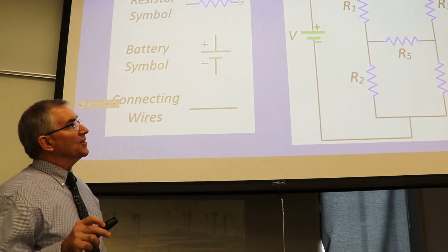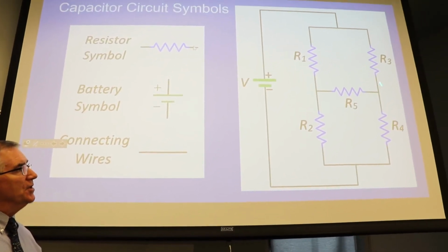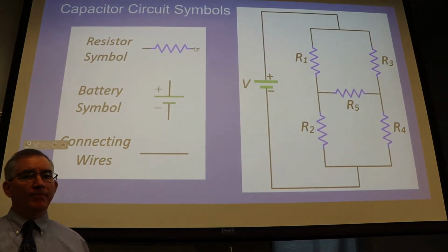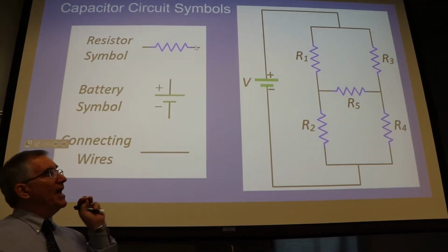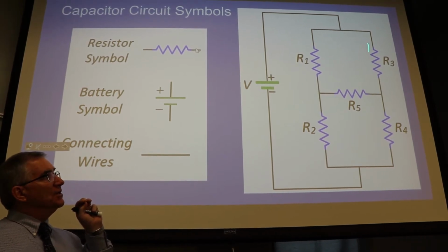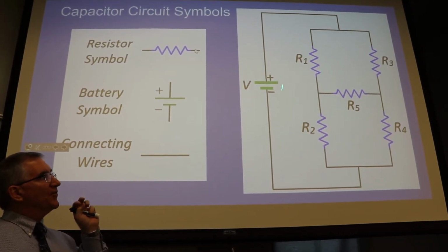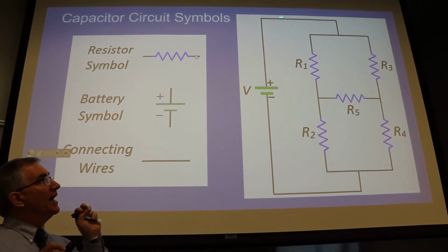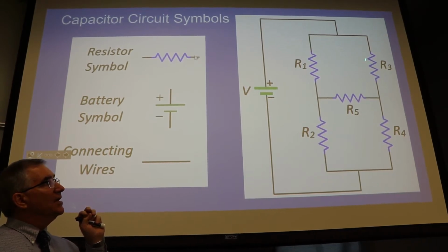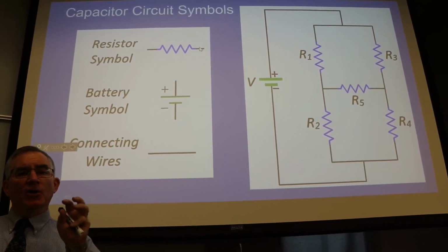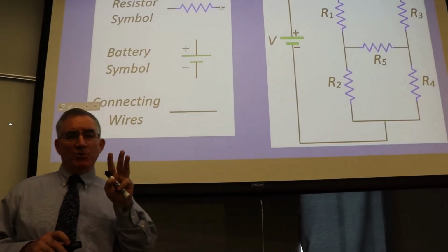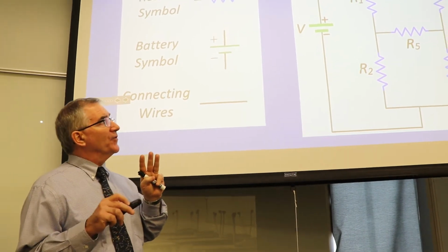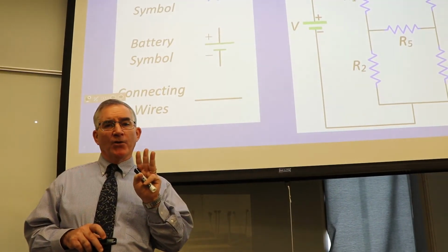And you can see in our circuit here, we got one junction here, another junction here, and a fourth junction right there. Now it turns out when you have three enclosed regions, you can see we actually have four regions, but three enclosed regions, and then there's a region on the outside. You can go all the way around the outside. That's how many equations you're going to need. So to solve this problem, since we have three enclosed regions, we only need three equations.